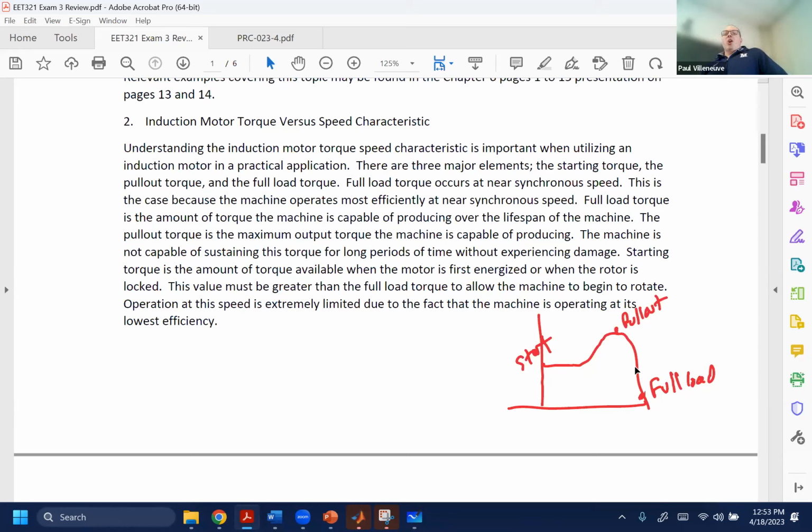All right. And all the protection that you see, and I can't remember who mentioned this in class, but you can trip motors out on stalling. But if you run it under slight overload conditions, 5 or 10%, the motor will do that as long as it can. But over time, it generates more and more heat until it has the potential to be damaged. So 5%, 10% is usually not an overload condition that the motor will trip out on.